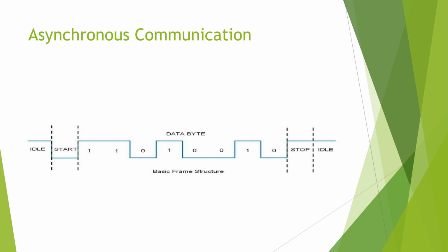So it is important, first you must know this one. Actually, the data frame. This is a data frame. Each and every character constitutes an 8-bit data frame. The starting bit is 0, and the end bit must be the stop bit, 1. The bits corresponding to that character are placed between this start and stop bit. So overall, total is called a basic data frame.